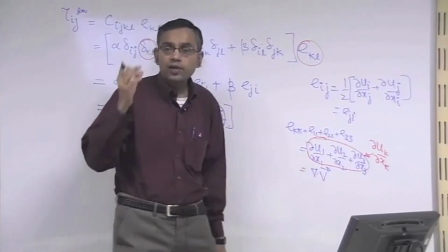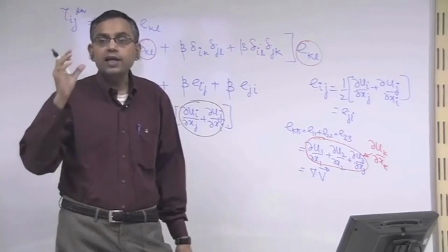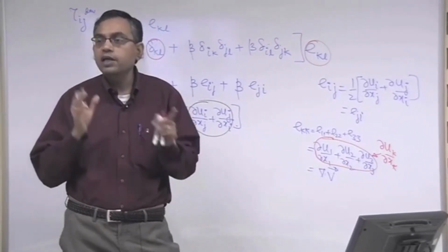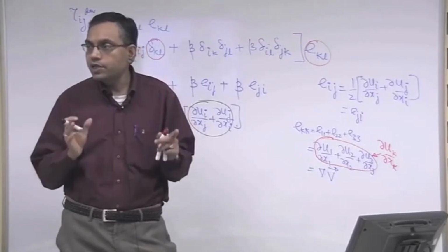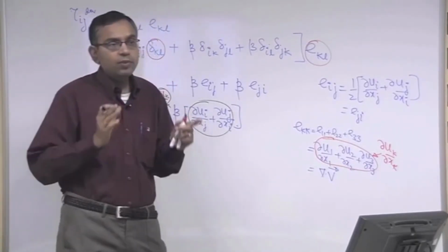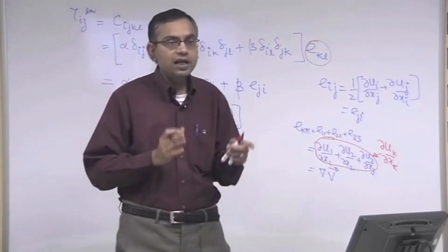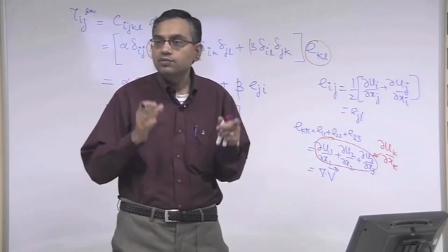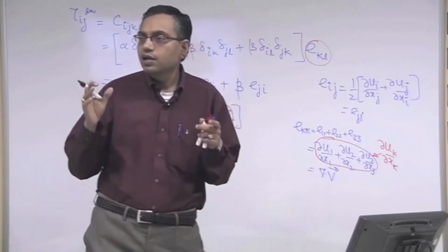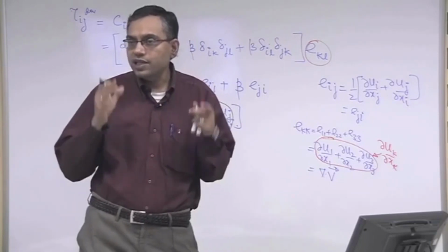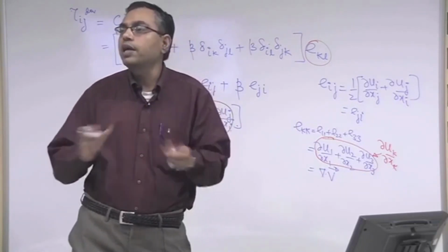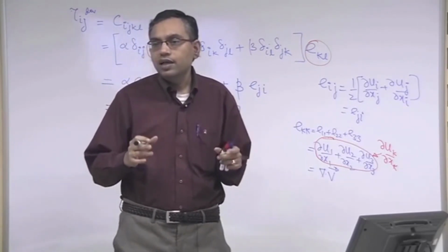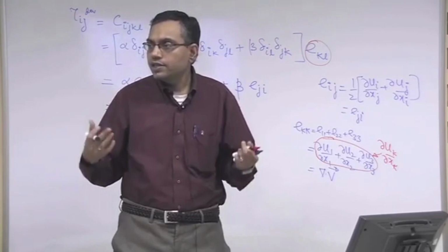Remember, incompressible flow is a pure kinematic consideration. There is a distinction between incompressible flow and incompressible fluid, and that must be understood very carefully. Incompressible fluid is a fluid where the density is weakly sensitive to pressure, so the change in density due to change in pressure can be neglected, and it can be shown that this holds for Mach number typically less than about 0.3.